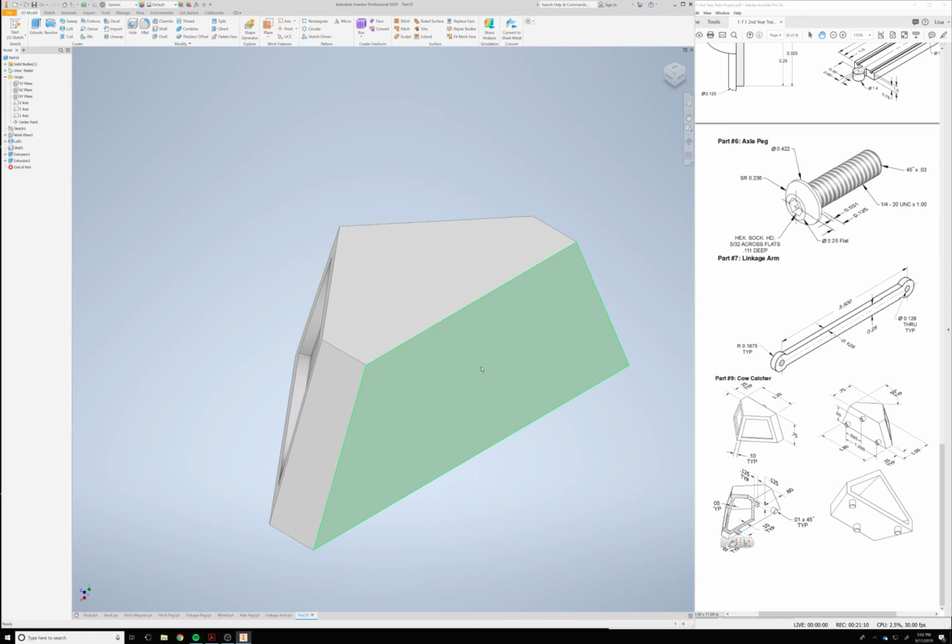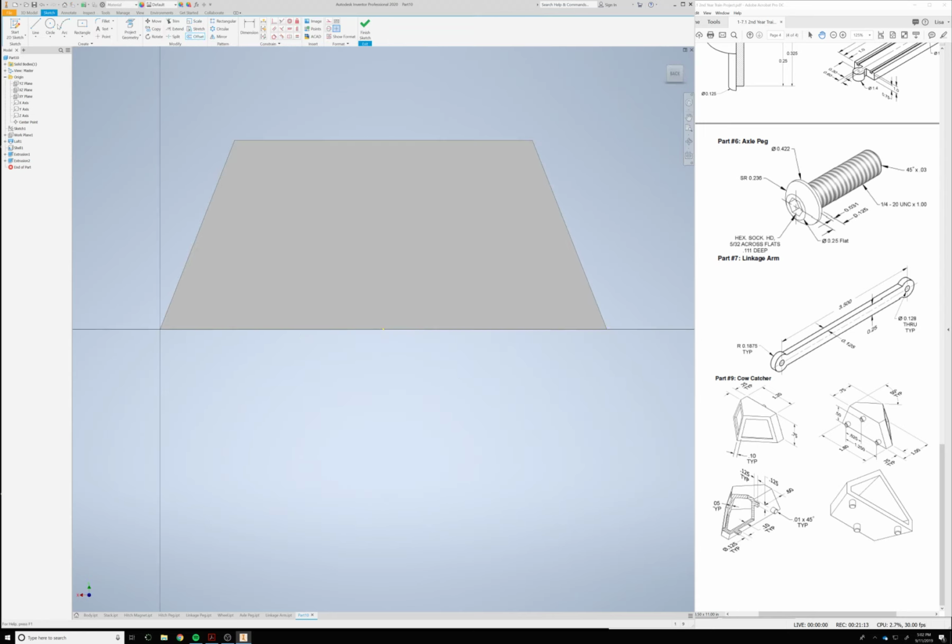Last thing that we need to do is put the little holes on the backside, or the little pegs. So the pegs are going to go in a triangular shape, and I'm just drawing them different random sizes. Going to click on my equals constraint, hit all three of those circles, and then dimension one of them. The dimension of this one circle is going to be 0.125. And I'm going to use my horizontal constraint to lock this in with this, and then use my vertical constraint to lock that in with the midpoint, or the origin.